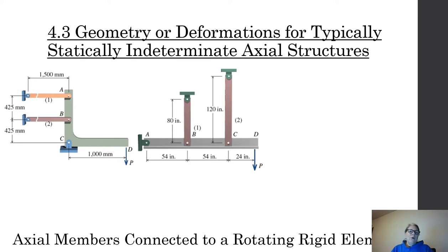The link is the same way, and you already had a homework where you had to look at a link. It didn't have two bars, 1 and 2. It just had bar 1. So when there's just one bar there, then you can determine the force in that bar, because we can sum forces in X, we can sum forces in Y, and we can get our X and Y at the pin and our X at rod 1. You've already had a homework like that. It was determinate. Now when we put that extra rod on there, number 2,